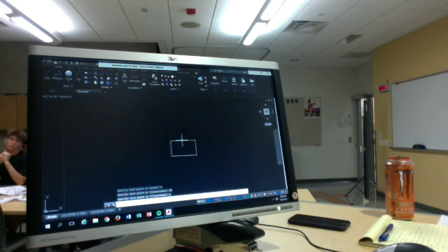And the point of that exercise is to show you that you don't necessarily need to be typing things in. You can just follow the grid, and it'll be giving you the proper increments. And you can draw using grid. You can draw using dynamic input. You can draw using your keyboard. There's actually a way to draw using entirely your keyboard. You don't even need a mouse, but that's so archaic that I'm not even going to waste my time showing you.